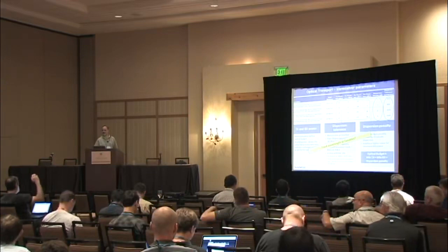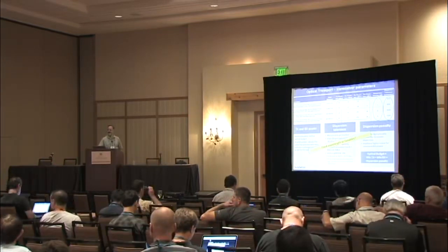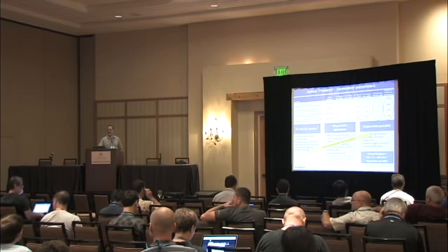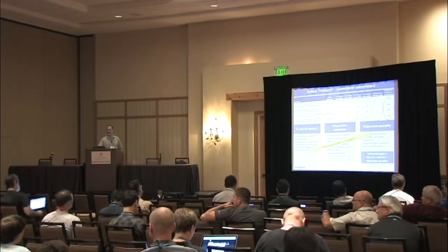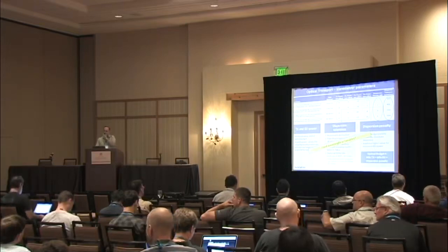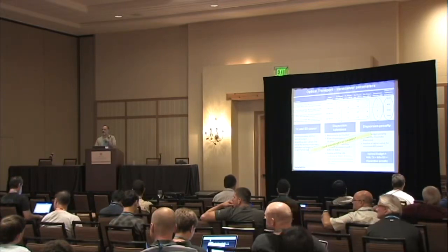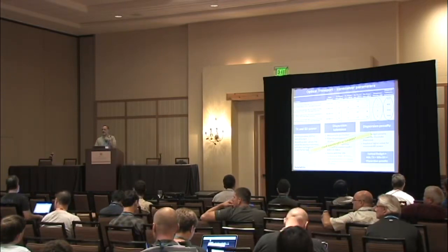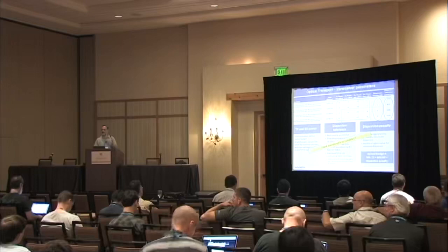We did fixed channels at one point, determined it was finally unworkable when we ended up with an unacceptably high failure rate among the transponders, combined with the fact that for reasons we still have not been able to explain, there were certain paths of fiber where we could not run certain channels because of whatever was going on inside the system. So, tunable is always for us.